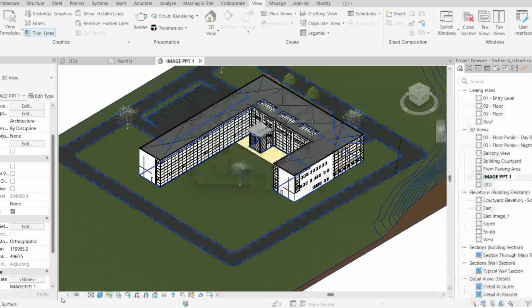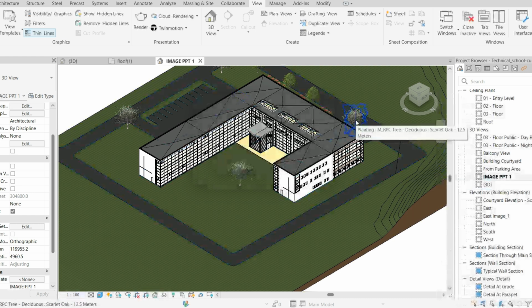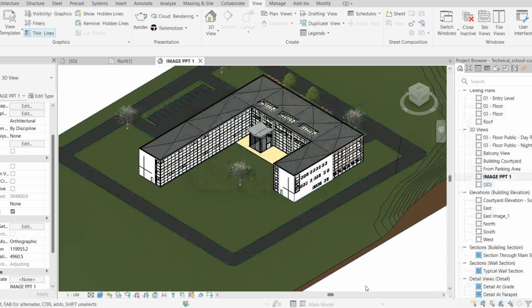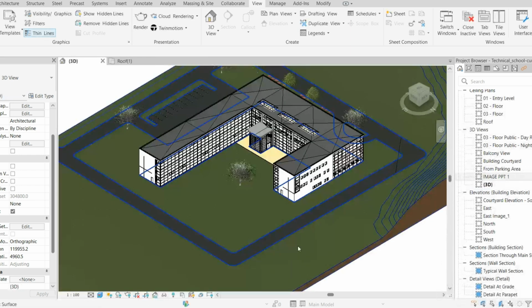In Revit, 3D views do not have a traditional scale setting like 2D views, such as floor plans or sections do. Instead, 3D views are typically viewed at a zoomed-in or zoomed-out perspective, and their display can be adjusted based on camera location and view crop settings. However, you can adjust how your 3D view appears in terms of scale or detail. As per the sheet size, you can set the view scale when you're placing views on sheets.